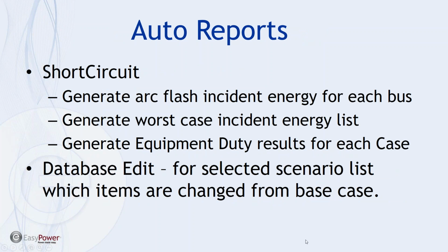Also, in Short Circuit, Scenario Manager automatically generates reports that compare arc flash incident energy for each of the scenarios and each of the buses in the one line, and at the same time can create the worst case incident energy list, showing in the list of buses only the ones that are the worst case.